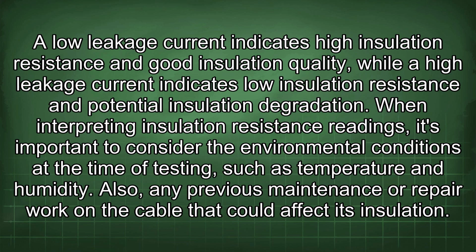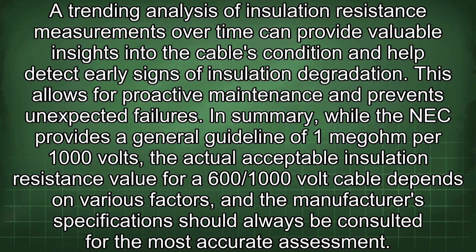When interpreting insulation resistance readings, it's important to consider the environmental conditions at the time of testing, such as temperature and humidity. Also consider any previous maintenance or repair work on the cable that could affect its insulation. A trending analysis of insulation resistance measurements over time can provide valuable insights into the cable's condition and help detect early signs of insulation degradation. This allows for proactive maintenance and prevents unexpected failures.